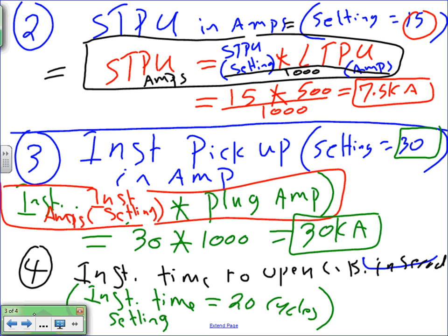Guys, with short circuit, there's 2 different kinds. I can grab phase A, phase B, phase C right at the service, bolt them together and flip the switch. That's what you're looking at right here. Or I can have phase A, phase B, phase C in a 225 amp panel way downstream, and flip the switch. That's completely different in value. So it's different based on how far you are from the service. It will get lower as you go farther away from the service.